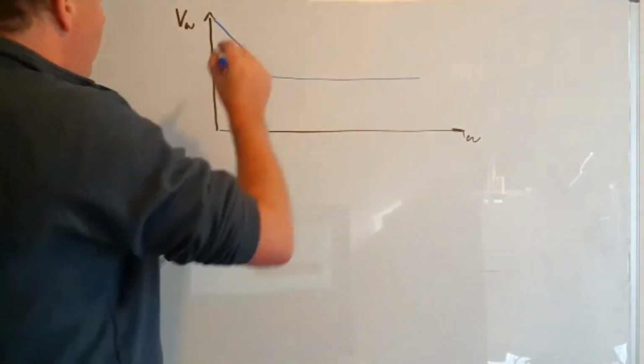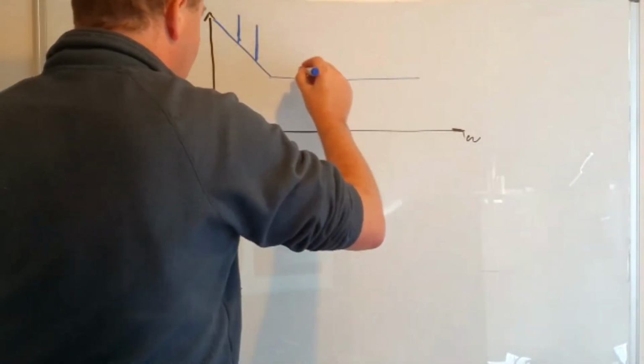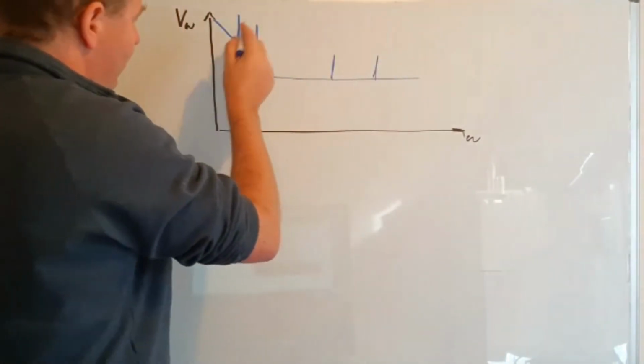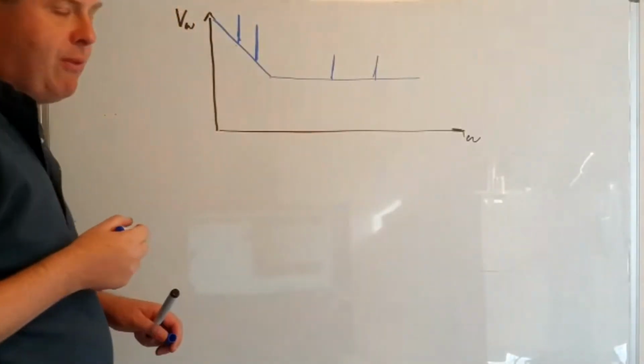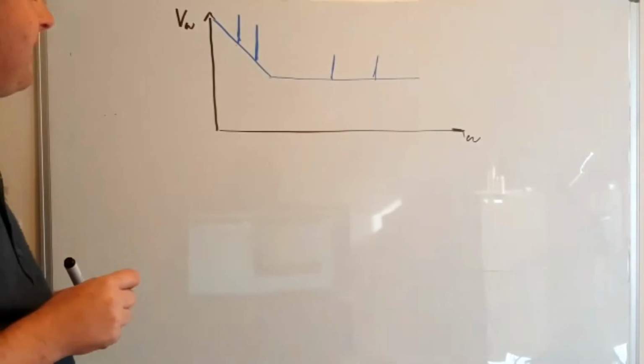And then what we expect to see is that at certain frequencies we get spikes of noise. So these might be, say, 50 hertz, 100 hertz, and then higher frequencies, which might be to do with, say, Wi-Fi signals or phone signals and similar.